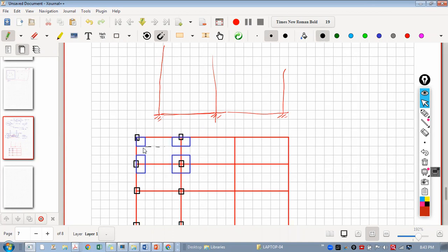Flat slab analogy, exactly. Only the pressure is upward, so you will have more, say, top steel here in this zone, then in this zone top steel, in this zone top steel, depending on the bending moments, as you know it is for vertical downward. It is vertically upward. That's it. Reverse case. So this is one case.